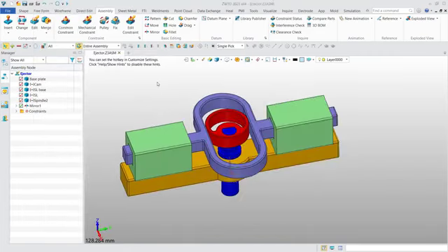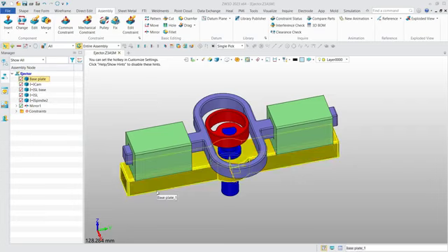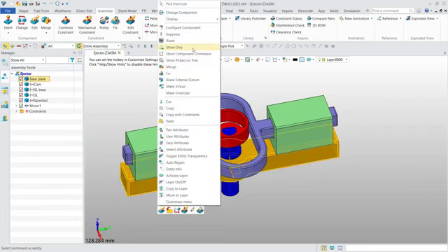Okay, last I'll show you the assembly features, which are assembly cut, assembly hole, assembly fillet, and assembly chamfer. And you can decide the feature only in assembly level or propagate to part level. Okay, first one is assembly cut, which means we can use one component as the cutter to remove material from another component. Take this base plate as an example.